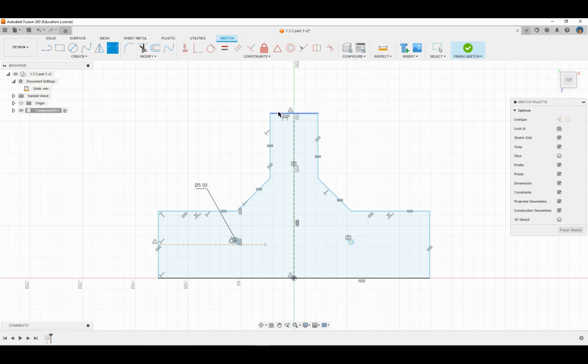The next dimension we're going to do is line 6, which is this top line here. I'm going to click on the line. I'm going to drag up. I'm going to click once, and I'm going to change this to 20 and hit Enter. Okay. Oh, and notice when I changed the size of this circle, this one did update properly. So that's good. Okay, change the size of this to 20.